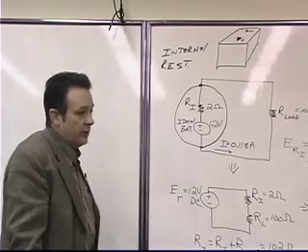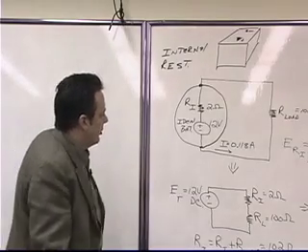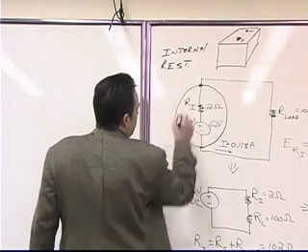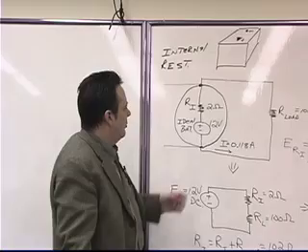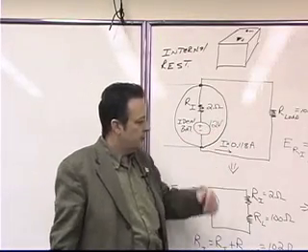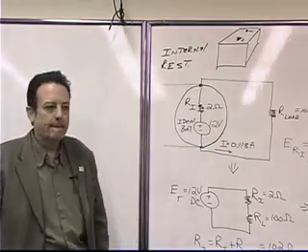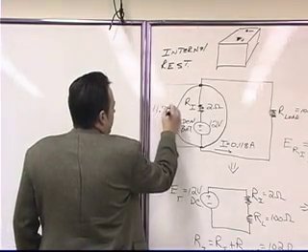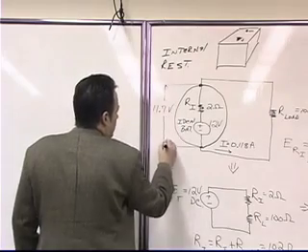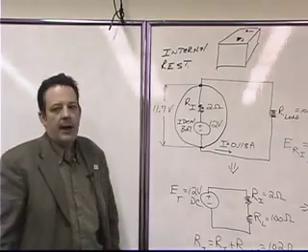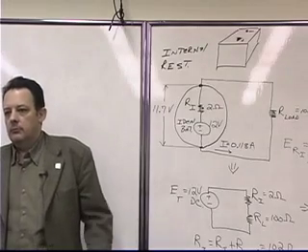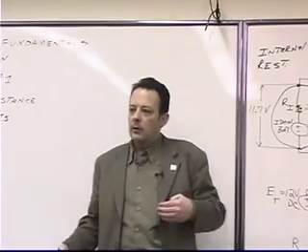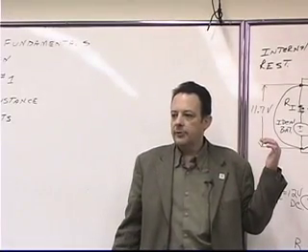All right. So, in this particular example, if we were to take a voltmeter and connect it between these 2 points right here, what would we get? What's 12 minus 0.236? 11.7 volts. So that's the actual usable voltage that we would get out of the actual source of power, because there's current flowing and there's a voltage drop across the internal resistor.